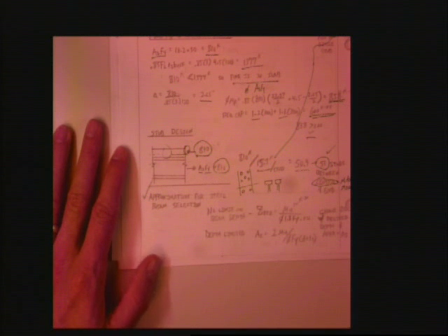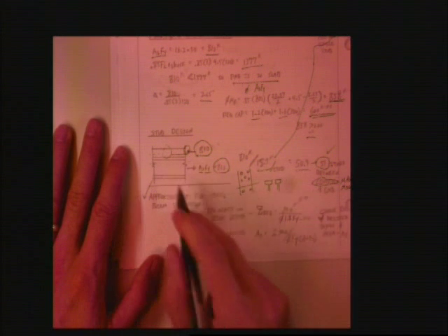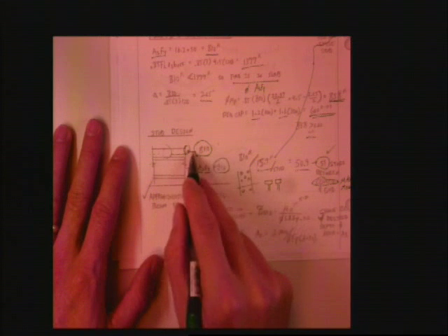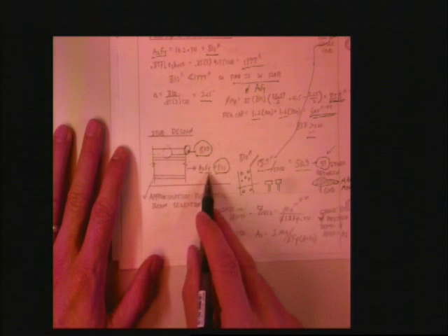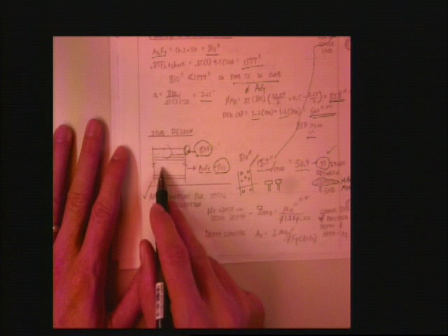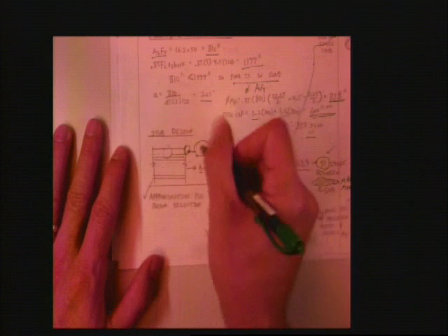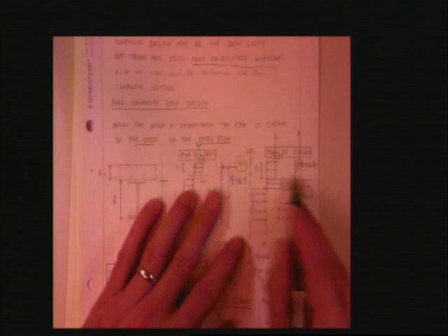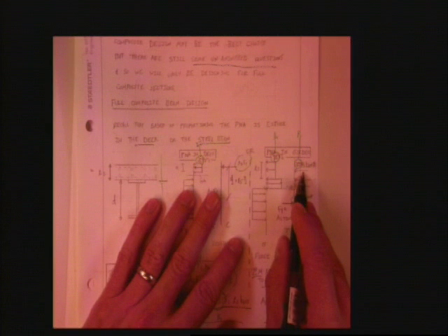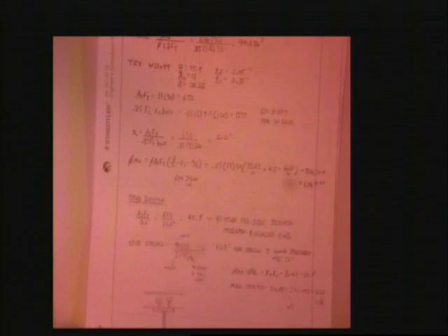It's an important point to understand that what Isabella said earlier is exactly right. The studs you have to design for the load that's in the deck. In this case, it was easy to find because it matched the load in the steel. In cases where the plastic neutral axis moves down, it's not so easy, and you have to actually do the Whitney stress block for the deck. Not that hard. You have to, in a sense, solve for this resultant, and that resultant is what you have to provide to design the studs. That's exactly right.